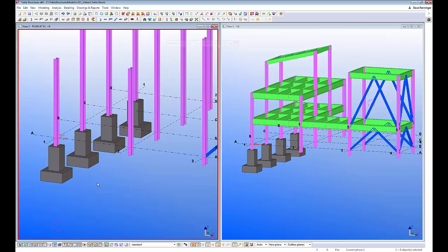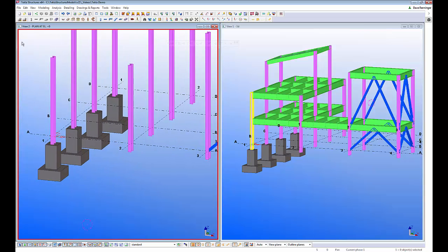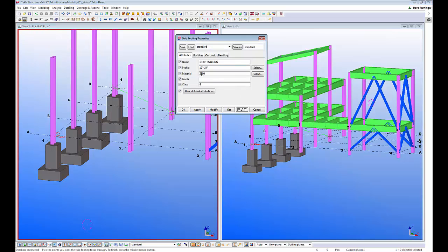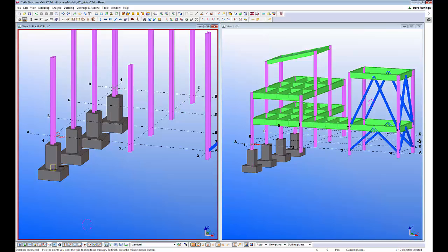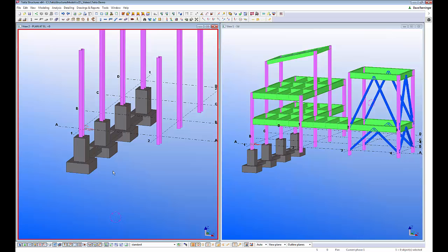All right, so now that I have all my parts in here, let's connect these with some strip footings. Up here on our concrete toolbar, if we double click on this, we can set up a different size for the strip footing if we need. With this one we do have to be careful where we pick, because it's almost like modeling a beam with the steel tools. But again, easy enough. I'm just going to pick the tops of my pad footings.